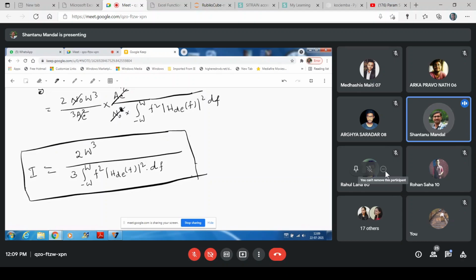And for the threshold effect, you always have to remember that it arises in case of the envelope detector and in case of the FM detector. But in case of a coherent detector, no threshold effect arises. In case of a non-coherent detector, no threshold effect arises. Only for the FM signal and the envelope detector, in these two cases the threshold effect arises.